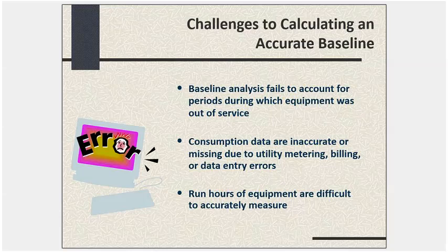Another thing is that people sometimes are of the opinion that any data they get from the utility company must be completely accurate. Unfortunately, that's not true. Sometimes utility data is inaccurate or missing. I've found there can be a data entry error on the utility side, a billing error, could be even a problem with utility metering on occasion. I found all of those types of errors, and consequential errors on occasion that were worth tens of thousands of dollars of revenue on an annual basis.